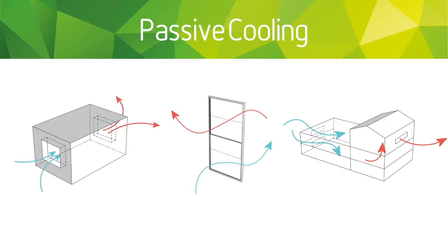You have a high level opening at the top of your building. It's used to draw in air through the low level and expel the hot air out the top. This works quite well because it doesn't rely on the wind, because it just uses natural buoyancy of hot air and cold air and the stack effect.